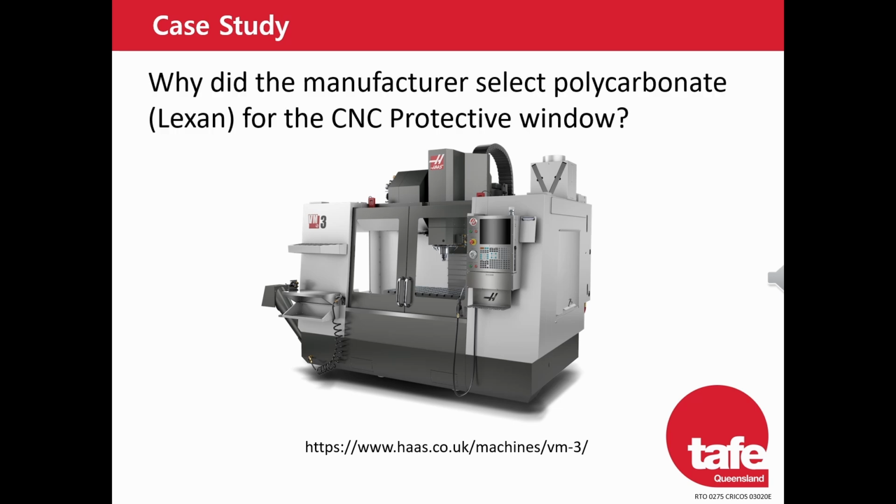Now that we have some understanding of the material selection process, I'd like to ask the question, in this case, why did the manufacturer select polycarbonate for the CNC protective window? Now, a few reasons would come immediately to mind as obvious, that being that the material needs to be transparent, optically clear, so that we're able to observe the workpiece as it's being manufactured.